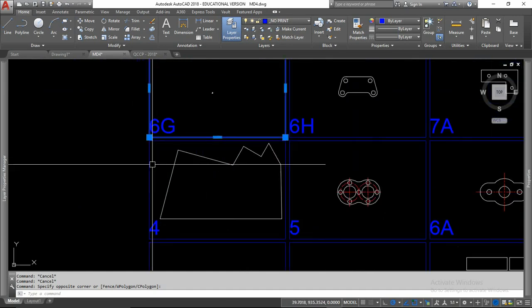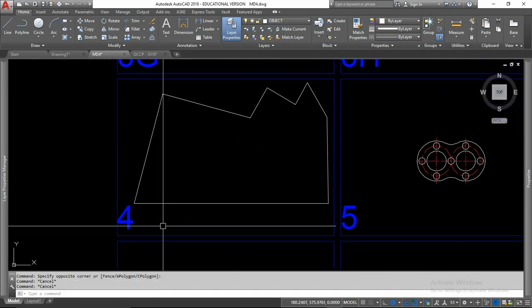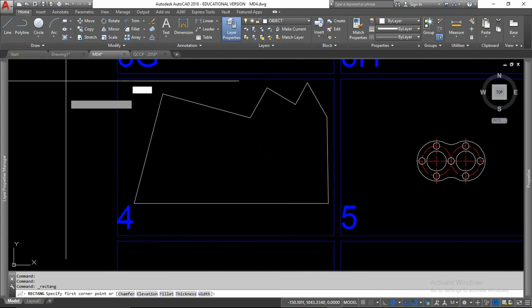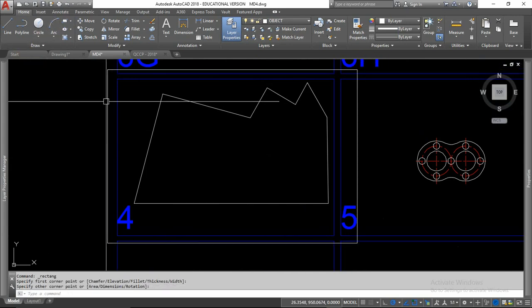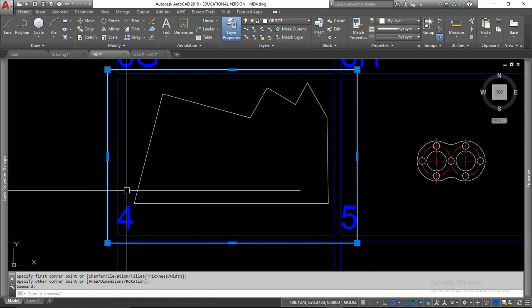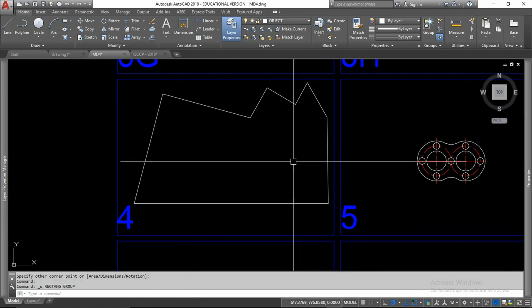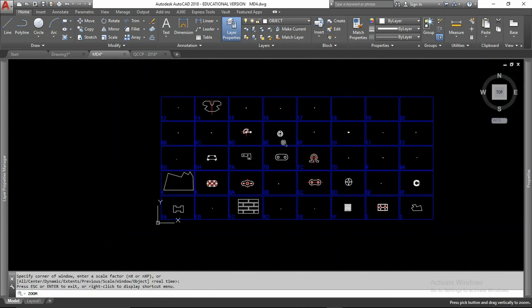I can look at this here, print this window as is, or select all of this window right here to print, and only the object inside of there will print. So no print layer is very useful, very useful.